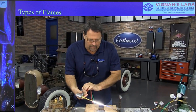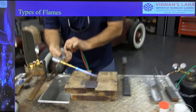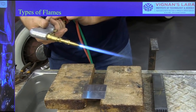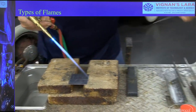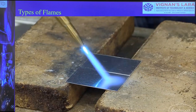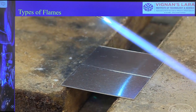I'm going to use a nice soft neutral flame. This torch is very good at low pressure. It allows us to do the real thin aluminum. I use a little Harris high temp on our flux. That allows me to get rid of the oxidation on our aluminum. And let's go ahead and weld this up. We're going to preheat, and we're going to dip in and dip out like we're TIG welding.